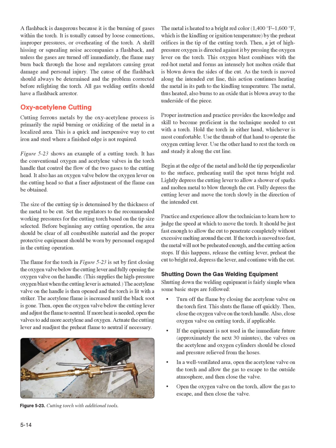Proper instruction and practice provides the knowledge and skill to become proficient in the technique needed to cut with a torch. Hold the torch in either hand, whichever is most comfortable. Use the thumb of that hand to operate the oxygen cutting lever. Use the other hand to rest the torch on and steady it along the cut line.